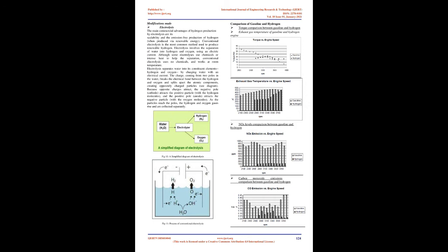The combustion chamber receives a charge of heated air from the cylinder and the injection of fuel begins an isochoric burn, which has increased thermal efficiency compared to a burn in the cylinder. The high pressure achieved is then released into the cylinder to work the power stroke. Meanwhile a second chamber which blankets the combustion chamber has had its air contents heated to a high degree by heat passing through the walls from the burn. This heated and pressurized air is then used to power another stroke of the piston in the cylinder.